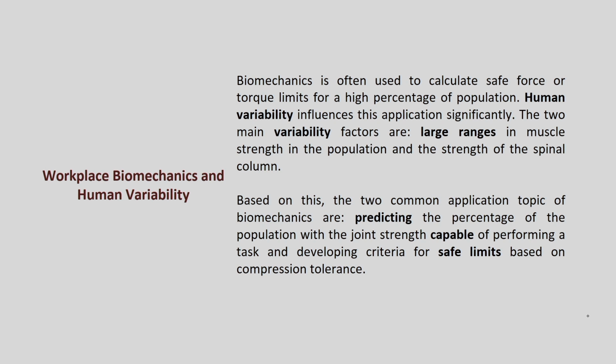Based on this, there are maybe two common applications we need to understand. One is predicting the percentage of population with a particular joint strength. Suppose we are talking about who has this much hand force or grip force, and we apply maybe 50% of that. Whenever a person operates a particular instrument, they need not use the maximum force, they can use 50% of the maximum. So, predicting that is important.